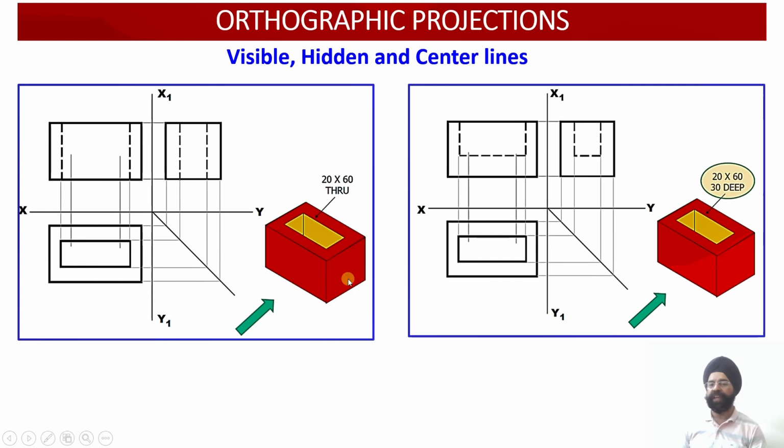So all three faces of the solid happen to be inclined to the plane of projection. And because of this inclination to the plane of projection, I am going to get a reduction in the sizes of the dimensions. So the shapes are not going to be preserved in the isometric projections.